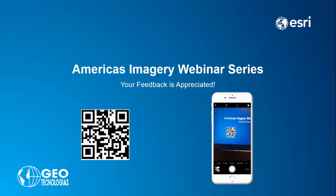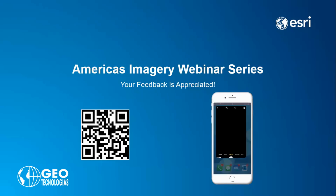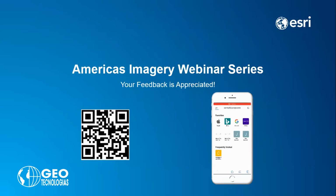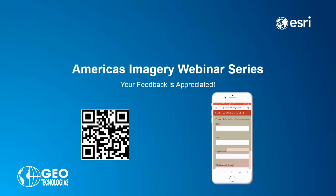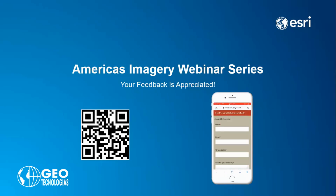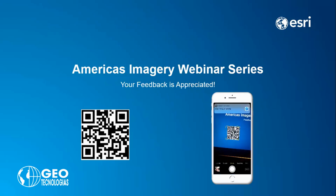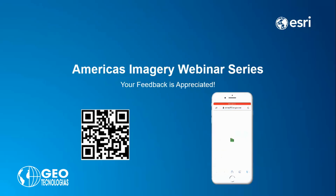by default, not all those sensors are on there and being captured. We're working on a way in SiteScan, our drone flight planning app, that will allow you to tap into, for example, the DJI hardware that enables that aircraft to capture that information. That's just like a metadata field. Once you have that metadata, basically as a CSV file, you can bring that into a full motion video product, and it'll use the bare minimum camera model information that's being collected by that drone. So it'll actually be part of SiteScan out of the box at some point this year. I don't know when the release date is.